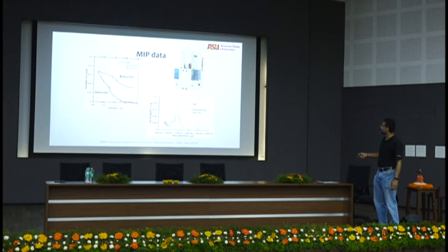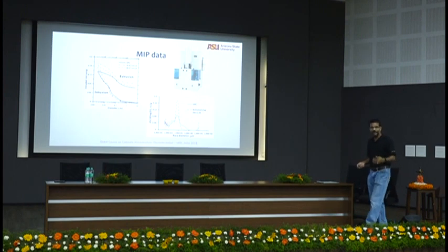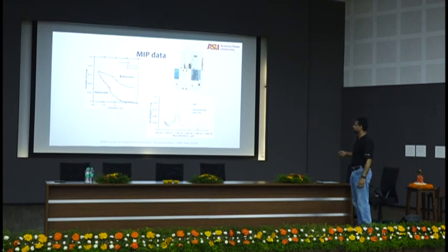And then, of course, I can find out how much volume in each of those diameters, right? This curve will tell me how much of volume is in this 0.1. Again, it's cumulative, so you have to subtract for every sequential step. But you can find out cumulatively, between 0 and 0.4, at 0.04, my size is about 0.018 microns. So you can find out the corresponding size of the pore.